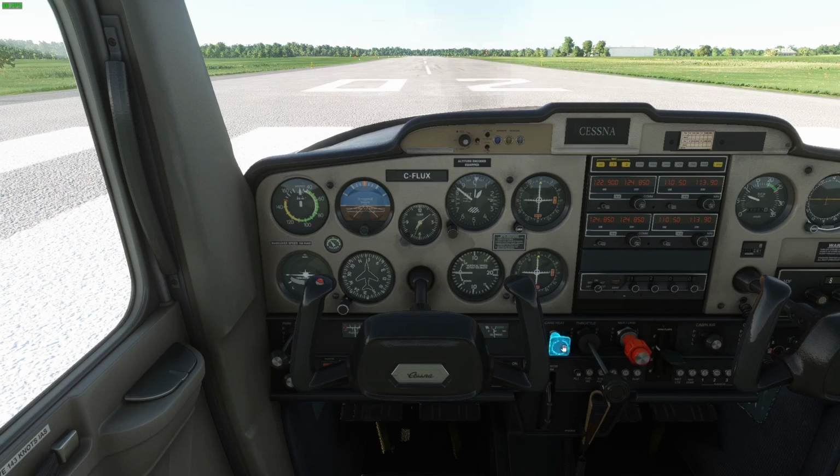It's a safety thing, so we'll have that on for all descents and all landings, anytime the RPM is lower than 2000 RPM. Mixture control, we'll leave it full rich for the circuit today because at 6,000 feet you have to thin out the amount of fuel going to the carburetor to match the less dense air that's going into the carburetor at high altitude.